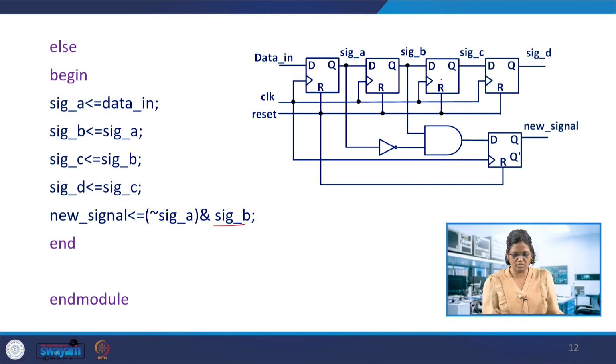there is only the passage of the clock that does this operation. So this is a shift register, and certain outputs of this shift register are taken to use in the next block, and which need to be registered. So this is a new signal which is formed from these, and because of this new signal, it is creating a flip flop over here. This is again the D flip flop. You can see this is the output which is called registered output. The signal is registered now. That means it will avoid the glitches, and it will work in synchronism with the clock of the shift register.